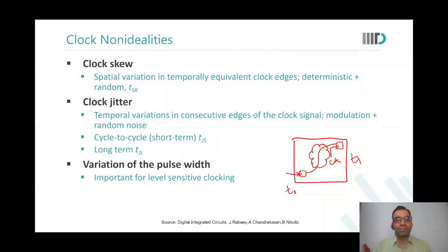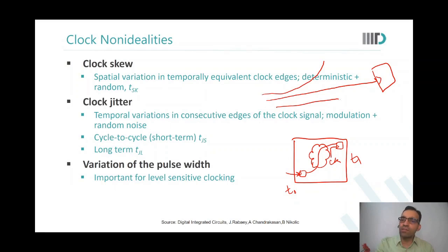Animesh, you were saying something? Sir, I was saying if at the same place also there's some clock. Now we're talking about the same flop where we say that due to, let us say, variations in the PLL through which you generated your clock or whatever, after some time it got heated up, or the wire on which this clock is reaching this flop has, in between, a set of other wires which it sees crosstalk with.